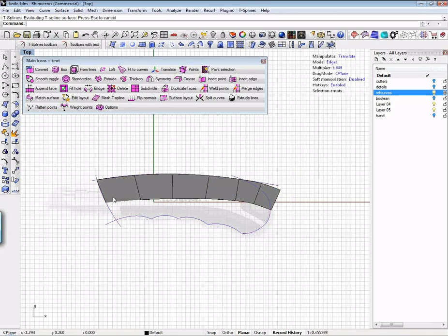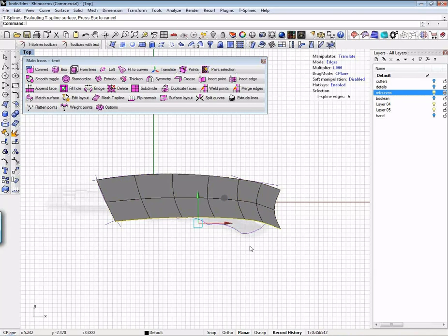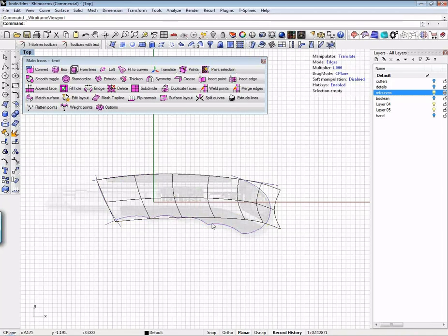And so I've got one line here. There's going to be a little bit of curvature in this model, so I want to have a detail line going down the center. So I'm going to grab this entire curve line by double-clicking the edge line, and then I'm just going to Alt-drag this whole thing down. And again, I'm not being terribly particular about where this goes because I can always adjust it later. And let me turn the shading off so you can see what's going on here.